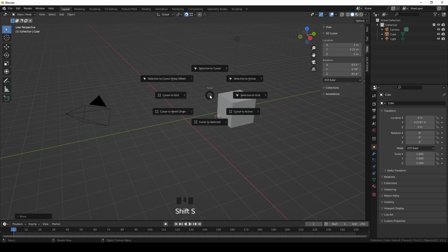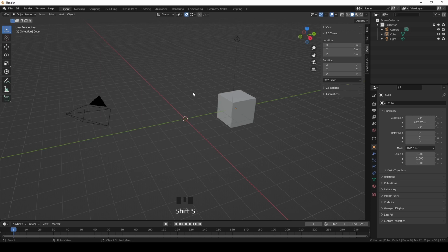Let's clear our 3D cursor to world origin, and also turn off your snapping options there. And we have a second thing in Blender, one of the more significant things to learn: object origins. What are object origins? All of your object modifications look for your object origin,